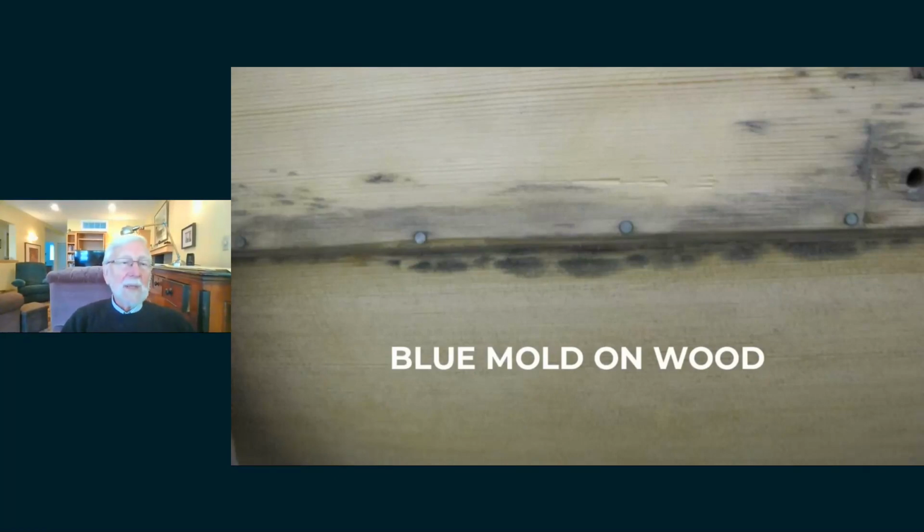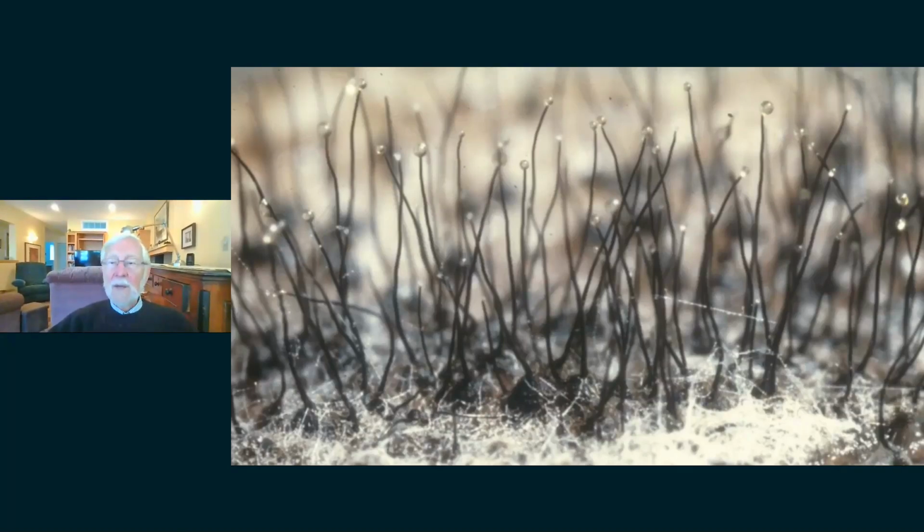So this is the one place I would say, this and in timber frame homes, where you really want to use a bleach. You can use oxalic acid to get rid of that. Otherwise, there's no reason to treat the black mold, the blue mold that you find in the lumber, if it's not going to be exposed. But it is unsightly. The homeowner isn't going to like his very expensive timber frame house to have that mold. And here's what it looks like when it's actually mature.